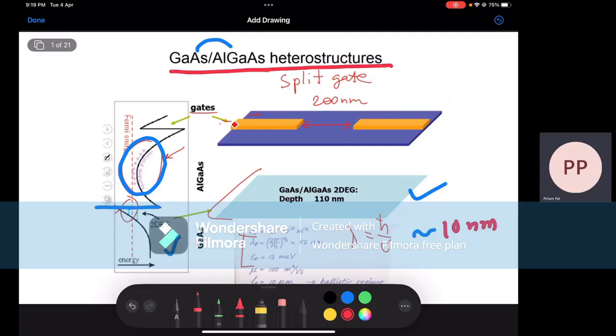Okay, so what is also important is that these structures are very ballistic in nature. Ballistic regime means that there is a very long mean free path, right? You can carefully engineer the semiconductors, for example by removing these dopants and not doping the channel itself, putting them a few nanometers away, which helps a lot.